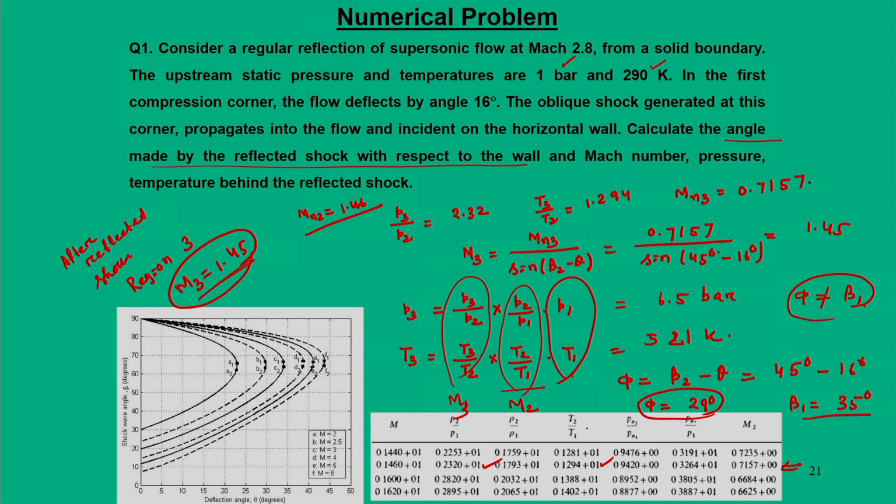So, the conclusion we can draw is that the shock wave is not specularly reflected. Because it is not specularly reflected, conditions 3 are different from condition 1. If these angles had been equal, the M3 condition would have been the same as M1.